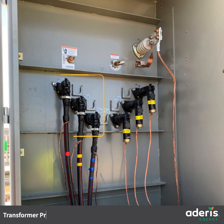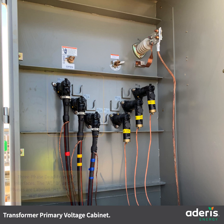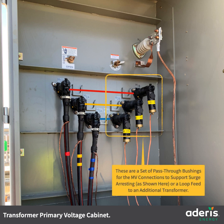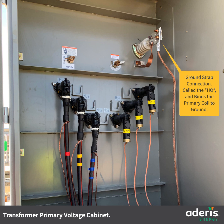Transformer primary voltage cabinet. Three-phase dead front MV interfaces. The A, B, and C phases are labeled H1, H2, and H3 respectively. These are a set of pass-through bushings for the MV connections to support surge arresting, as shown here, or a loop feed to an additional transformer. The ground strap connection, called the HO, binds the primary coil to ground.